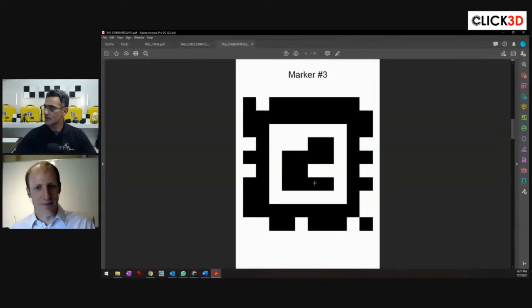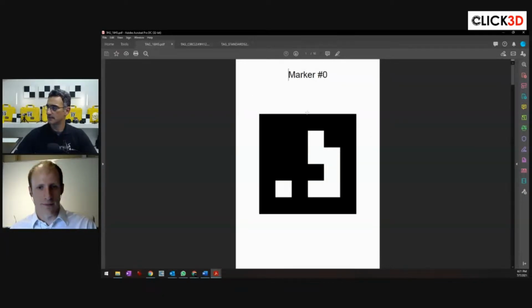So what kind of things go wrong with, for example, some of the lower ones, let's say tag 16? What's a typical problem that you see in computer vision with something like this? So the way the algorithm works is it looks at your image and finds all the different quadrilaterals in the image. It treats each one of those quadrilaterals as a possible real tag, and tries to read out what the data bits on the tag are. If by chance it happens to get a pattern of bits that matches this tag, it'll report a tag detected there, even if it's not actually a tag.